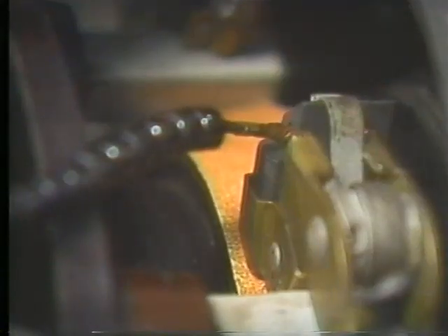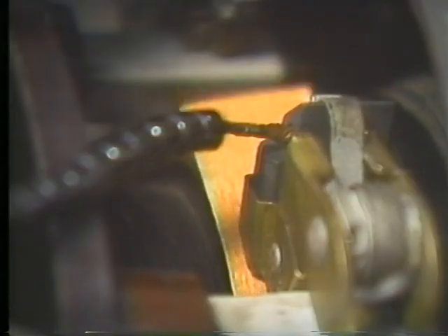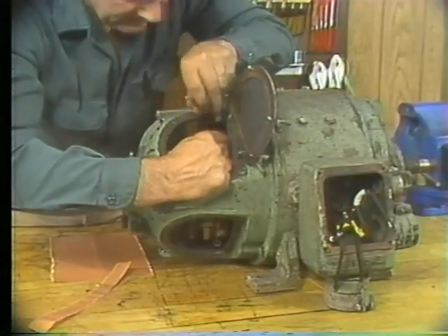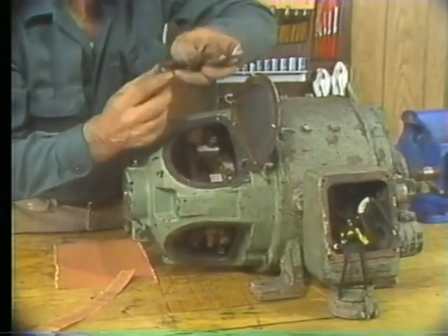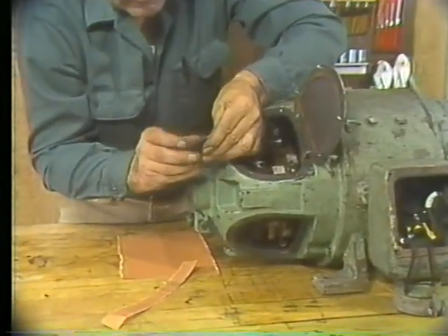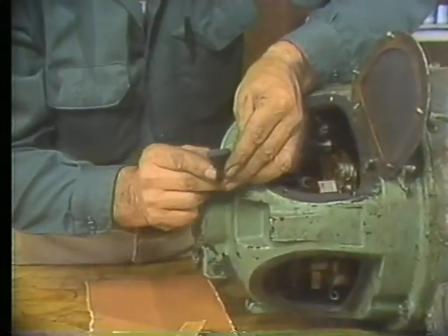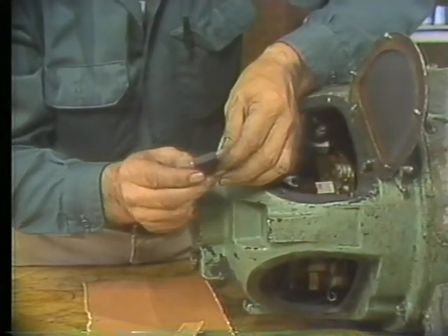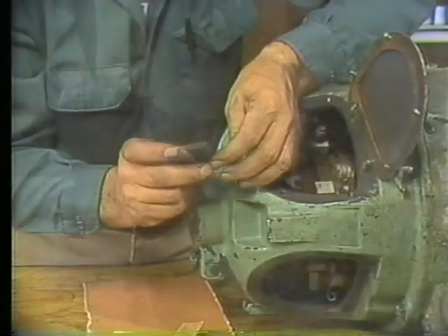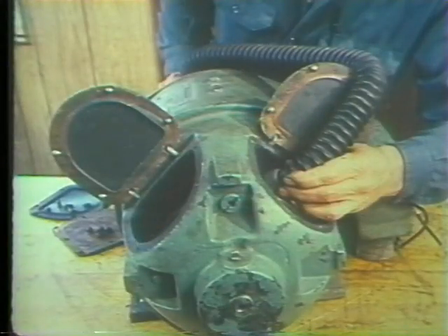Rotate the armature slowly in the direction of motor rotation until the flint paper is out from under the brush. Then remove and inspect the brush. Repeat the procedure until the contact surface of the brush has the same shape as the surface of the commutator. When you've got 100% contact, the job's done. Be sure you remove any carbon dust in the motor afterward. All right. At this point, your brushes are ready.